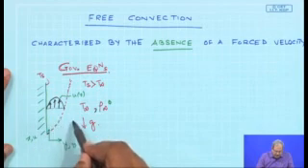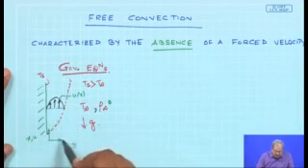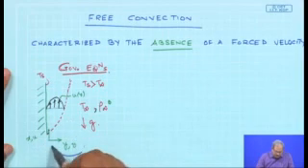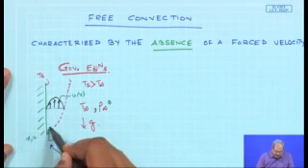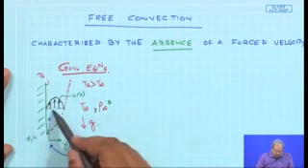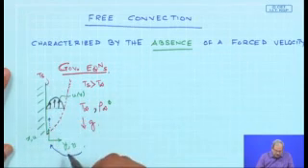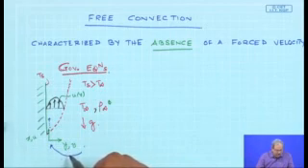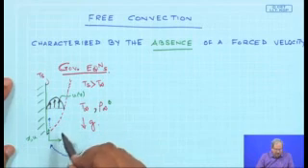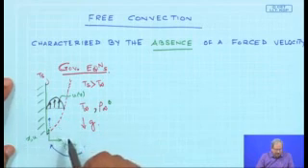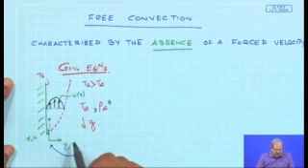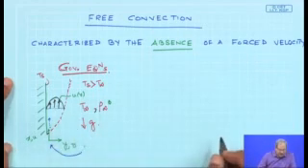As it rises up, this fluid is going to be replaced by cooler fluid from here. So you have a cooler fluid from over here, and then the process would start once again. So the hot fluid near the wall rises towards the top to be replaced by cold fluid from the ambient. So this is what is known as free convection, and free convection is also classified according to whether the flow is bounded by a surface, and free boundary flows may occur in the form of a plume or a buoyant jet. Okay, so let's write the equation.